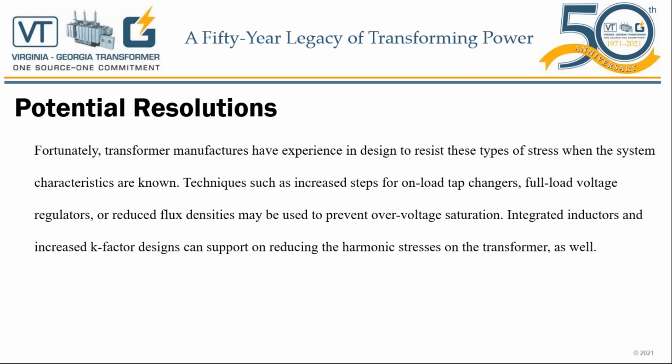Techniques such as increased steps for on-load tap changers, full load voltage regulators, or reducing the flux densities, we may use these to prevent overvoltage saturations. Integrated inductors and increased K-factor designs can also help reduce the harmonic stresses on transformers as well.